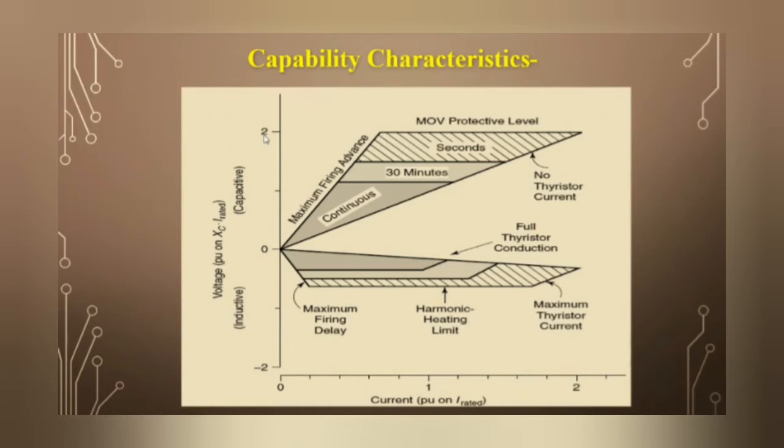Why is this restriction imposed? This restriction is imposed in the form of a maximum advance angle beta. And the minimum TCSC capacitive reactance is obtained when the Thyristors are blocked. If we operate the TCSC in a blocked Thyristor mode, at that time we get the minimum TCSC capacitive reactance, in the absence of Thyristor current flow, and XTCSC is 1 pu.